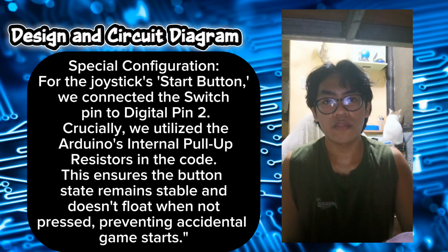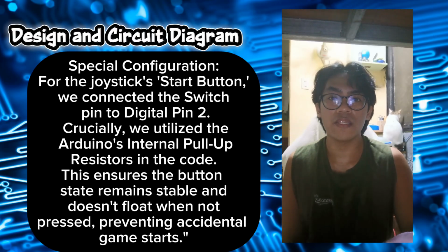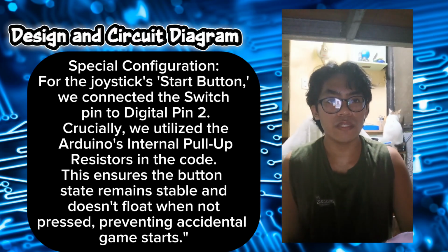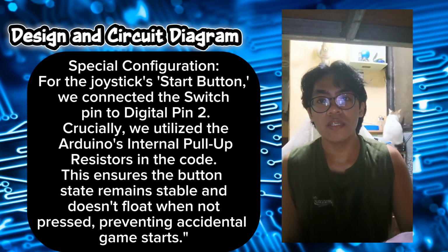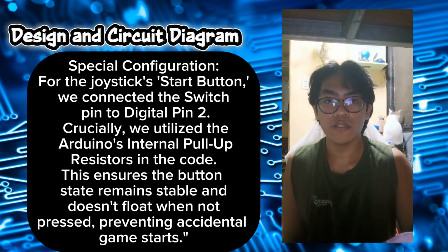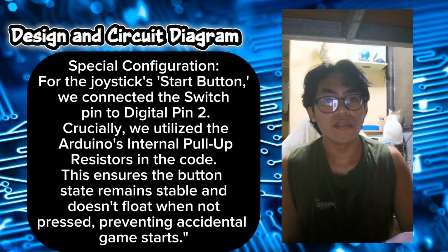For the joystick start button, we connected the switch pin to digital pin 2. Crucially, we utilize the Arduino's internal pull-up resistor in the code. This ensures that the button state remains stable and doesn't float when not pressed, preventing accidental game starts.